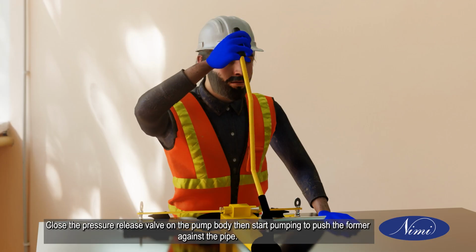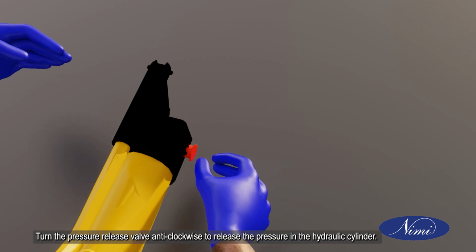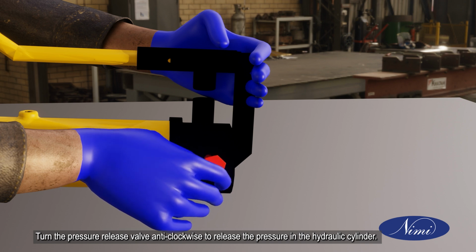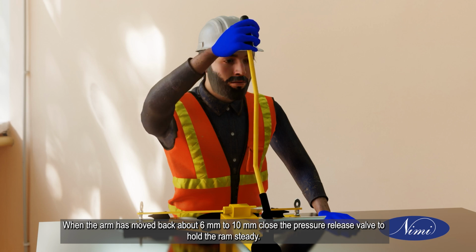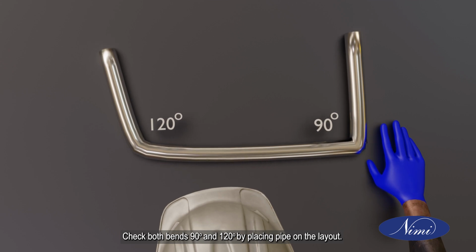Close the pressure release valve on the pump body, then start pumping to push the former against the pipe. Turn the pressure release valve anti-clockwise to release the pressure in the hydraulic cylinder. When the arm has moved back about 6 mm to 10 mm, close the pressure release valve to hold the ram steady. Check both bends 90 degrees and 120 degrees by placing pipe on the layout.